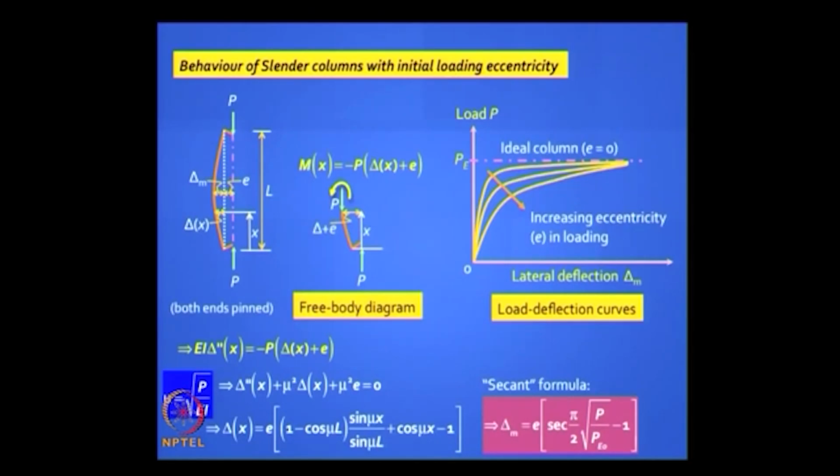You have a unique solution, and what is interesting is that all those lines you can see, if you look carefully, if your column is stiff, you are probably going to get this curve. If your column is slender, you are going to move inward. You get it?